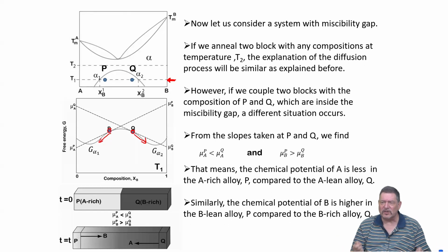If you use concentration gradient, you have to make sure you understand your system very well, because there might be a minus necessary to account for uphill diffusion going the wrong direction according to how the concentration gradient is present in your material.